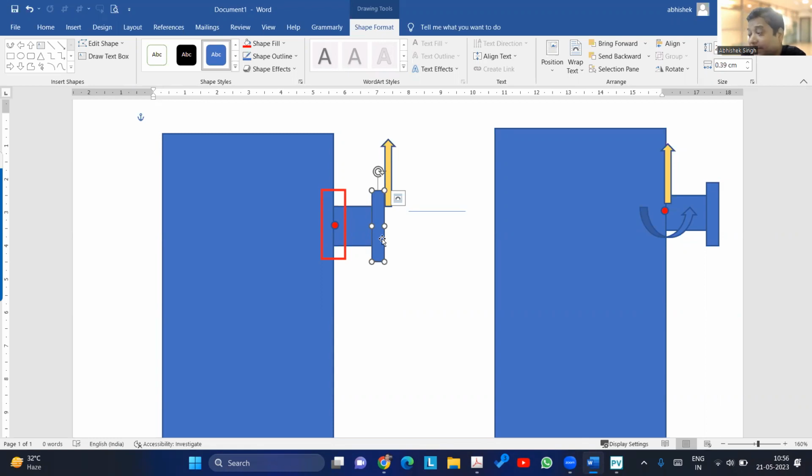So Abhishek is saying the pressure retaining capacity will reduce, because we have selected a flange based on rating, which is determined by pressure and temperature. Okay, these are standard flanges. Only pressure and temperature are considered, and based on that, these are created. They are standard items. It has never been considered that there will be some extra load coming on them.